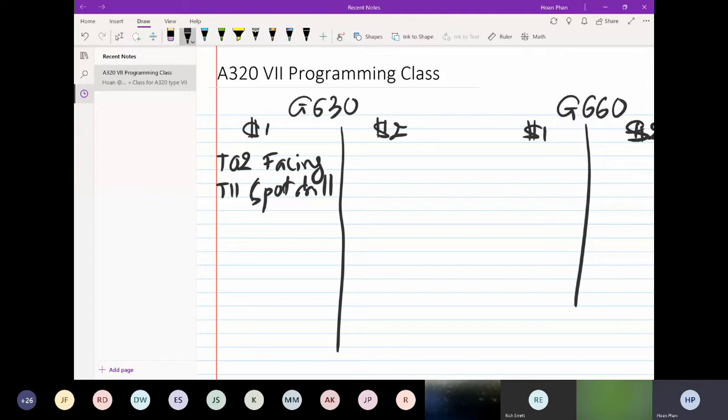Okay, so the spot drill right here, as we can see, look at the part, and then we can see the hole right in the middle. The size is 166. So the spot drill right here, we can use 187. It should be enough. It's gonna give you a little bit of chamfer on the ID. So 187, I think it should be enough.